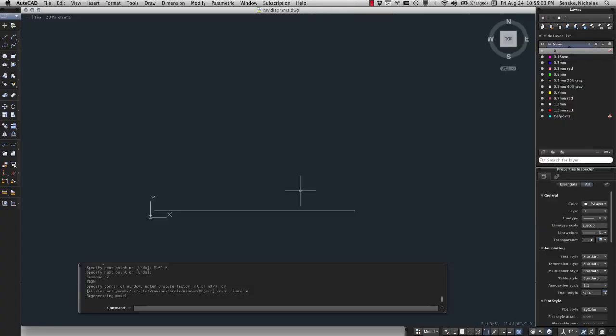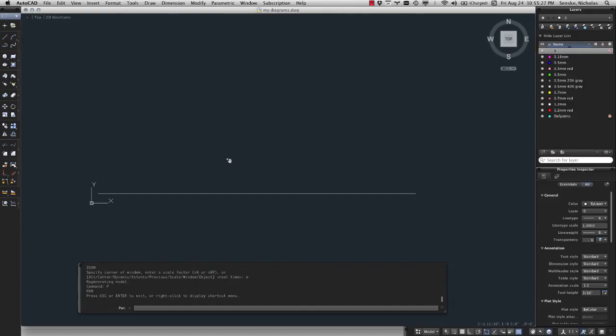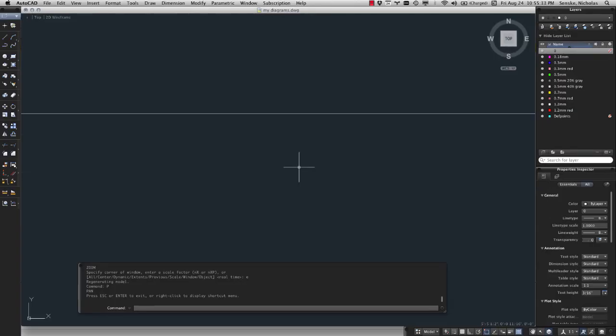You'll notice a couple of things. One, zoom you can accomplish with the Z command, the zoom command. You can also use the mouse wheel in and out, but sometimes it has limits, like it doesn't quite reach all the way. Panning is accomplished with the middle mouse button, or P for pan. I can press P, enter, and that'll let me pan, and then I just press enter to quit. So pan and zoom, those are big features.